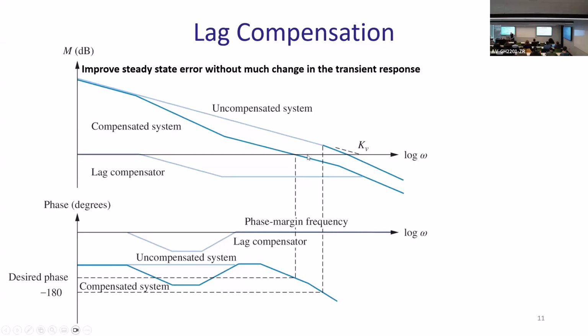So let's say this was the original plot, right? So this is uncompensated system. You had some plot here, okay? So it was in that neighborhood where you have crossover point, right? And your phase margin was horrible here, okay? Probably negative phase margin, which means it's even not stable in that case in closed loop or something like that, or very small. Okay, so it's really minus 180, it would be somewhere here, right? Crossing point, original crossing point. So you have no phase margin, essentially, right?